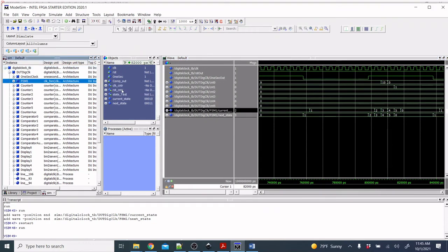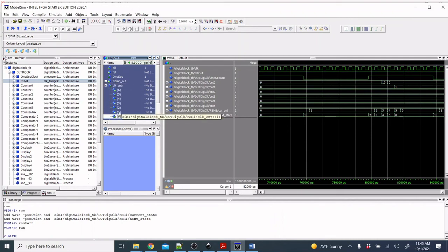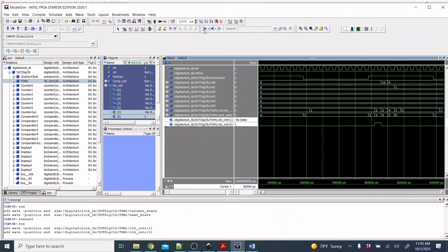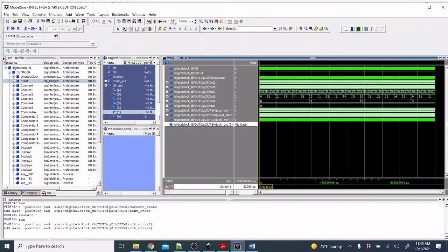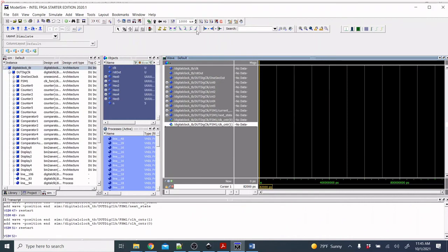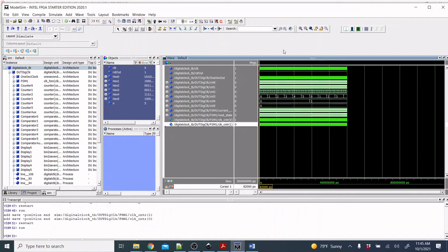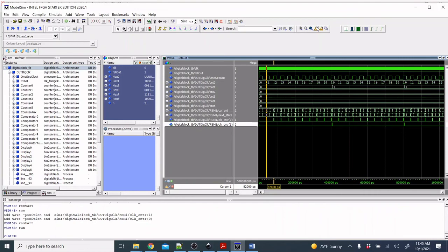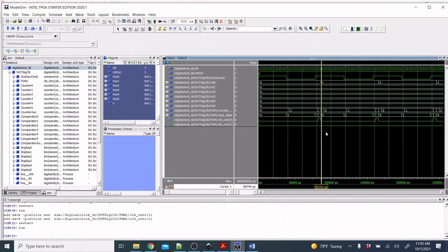Let's just select the reset or the enable of the counters, and we're just gonna check the first two. Okay, let's move this one. This is counter 0, counter 1, the enable. So we're gonna restart. Then we're gonna simulate for half the time we were doing it. Simulate. Okay. So let's zoom in. If you see, we count. This is the way to check.